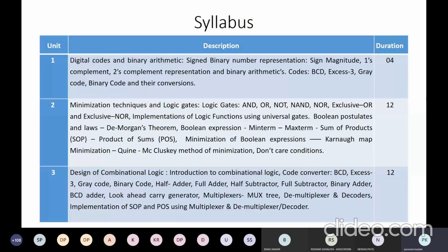the circuit. So from the construction point of view, every sequential logic circuit should have some kind of memory element which will store the condition of the circuit at that time. So the basic building blocks for combinational logic circuits are logic gates, and the basic building blocks for sequential logic circuits are the flip-flops, which are 1-bit memory elements.